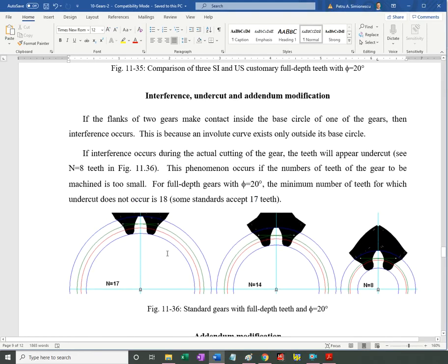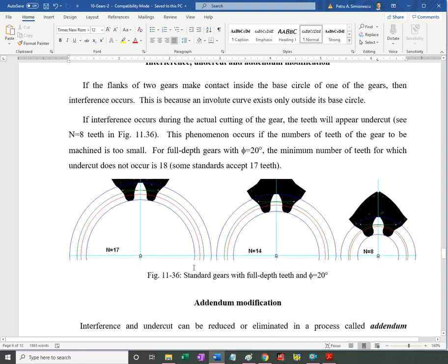Of course, if I take the cutting tool and mesh it, or stub it, that is, take off of the tooth to allow for that clearance, they can mesh because I enveloped the tip of the tooth below the base circle. But in general, teeth that are put into mesh, same module, same diametral pitch, are supposed to mesh. But if I have contact made inside of the base circle, this is not going to be a correct contact.